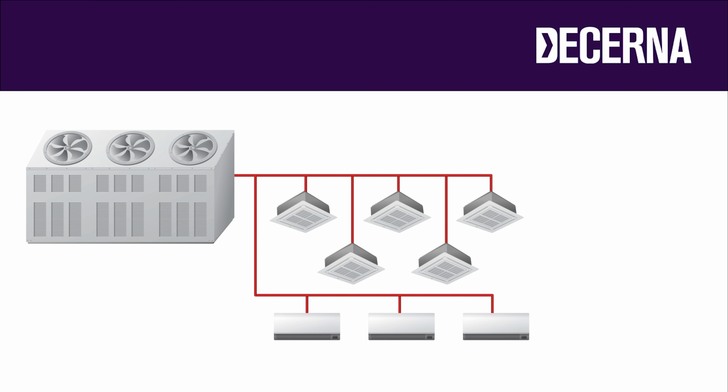Or for larger buildings, it's more common to see heat pumps that operate from a centralised plant that combines the evaporator, condenser, and a ventilation air supply fan. Heat from these package systems is distributed around the building through a system of air ducts.